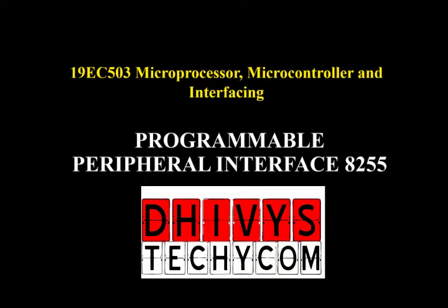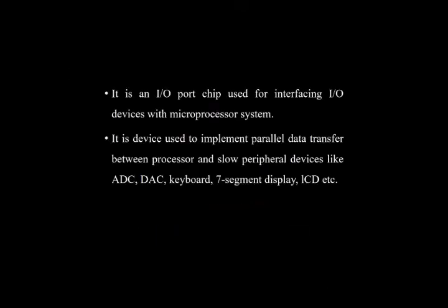Before getting into 8255, we just want to know what 8086 is all about and where it has been utilized. So 8086 is a 16-bit microprocessor that helps us in doing all basic arithmetic and logical operations. But 8086 is found to be inefficient in connecting external devices to it. So to provide an external interface, we want to have another interfacing connection. One such connection is 8255.